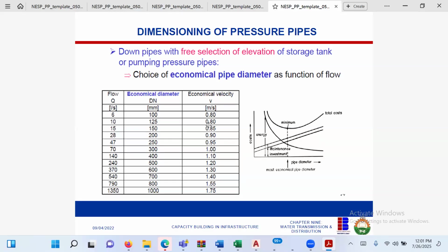So the same thing applies to water design. Sometimes you don't need to crack your head. You just check what's the flow rate I got. This is the minimum pipe design. And most times it works. It works. That's why some designers will go and put 50 mm pipe everywhere.